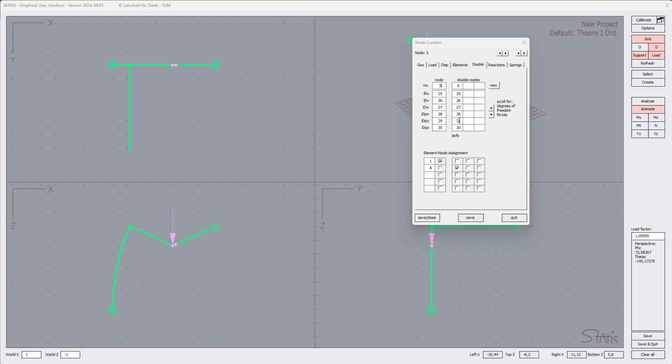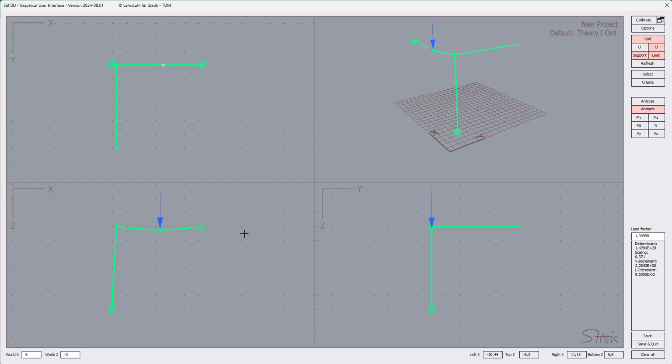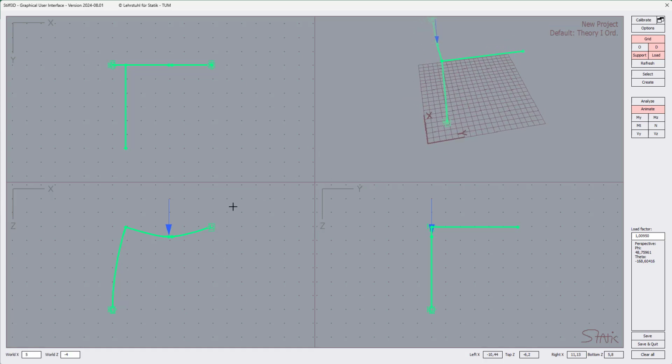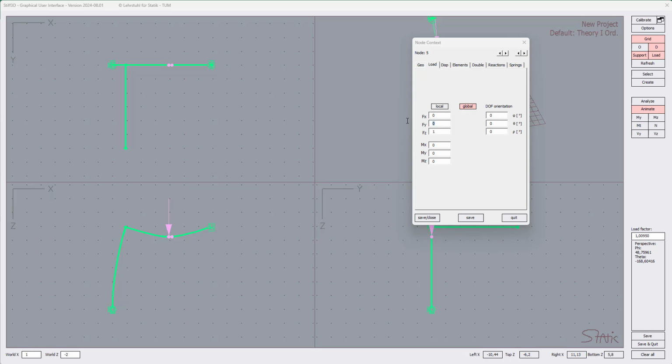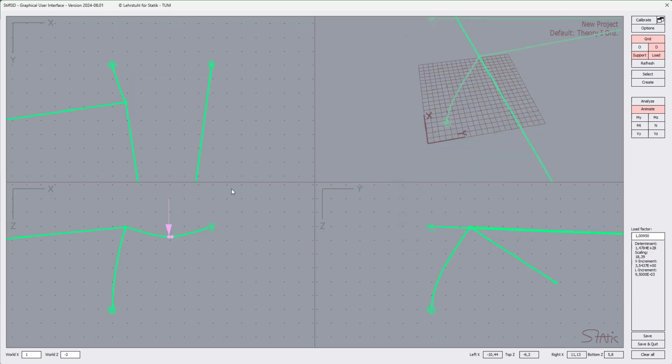Going back here, closing it again by giving the same numbers. But let's say, okay, let's open the rotation around the z-axis. If we do that, of course nothing happens with respect to the bending in the xz plane, as we had before. But if we now apply a little load in the y direction, let's say 0.2, not so much, because the structure becomes soft again.